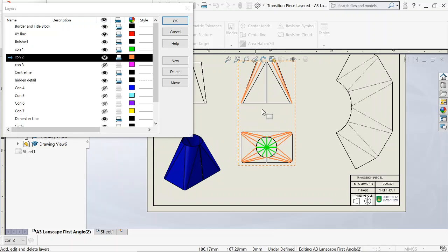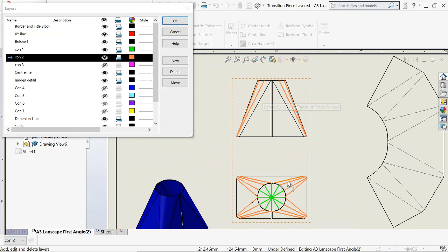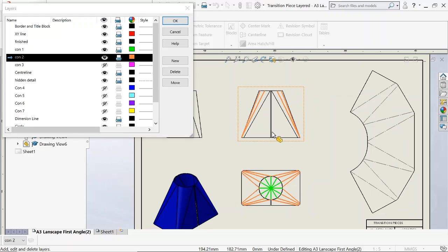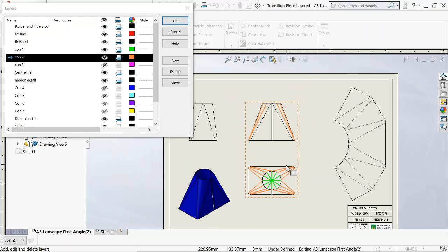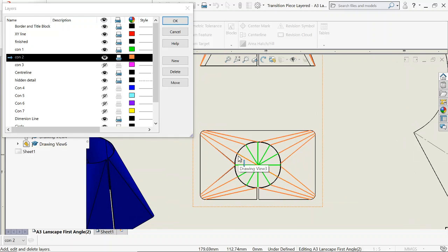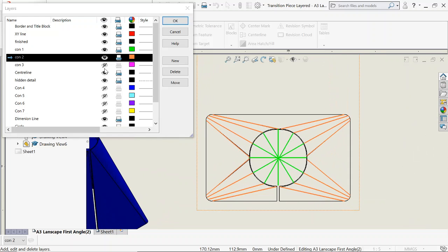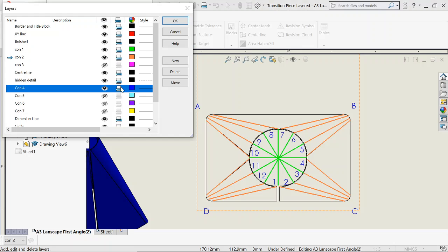So when they have that drawn in plan, they bring their lines up to elevation. So we bring up this line and this line straight up and join it back to the corner, and that's it completed in elevation. After that, we must label our drawings so we don't get confused as we move on with the question.